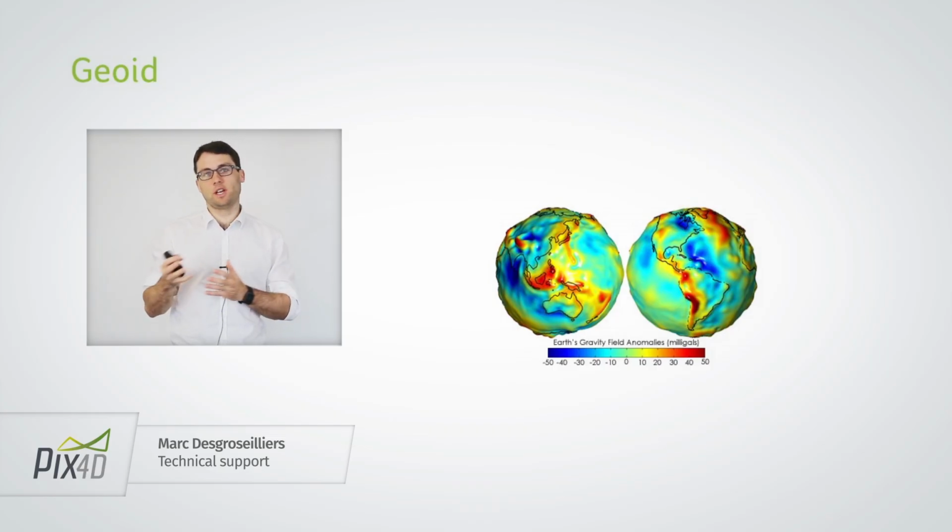So there's really a trade-off. In a sense, the ellipsoid is simple and might have larger differences with the actual Earth, but it's very easy to compute. Whereas the geoid is more computationally intensive, but it's also more accurate.